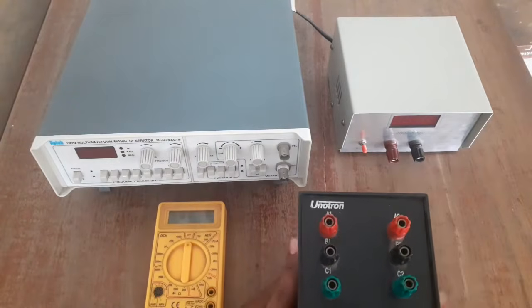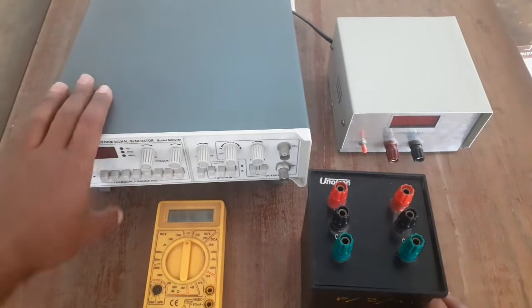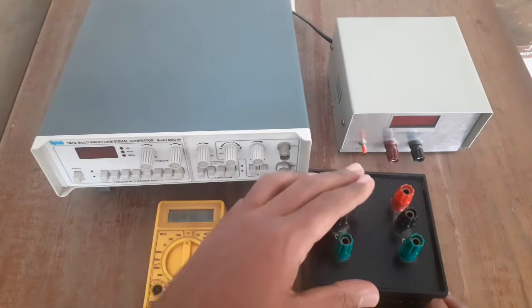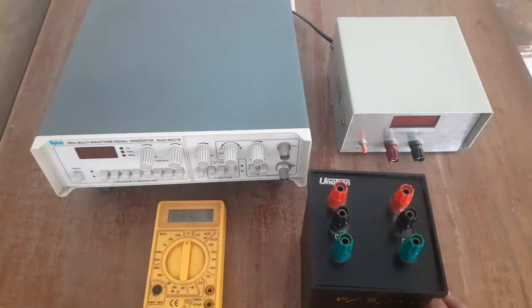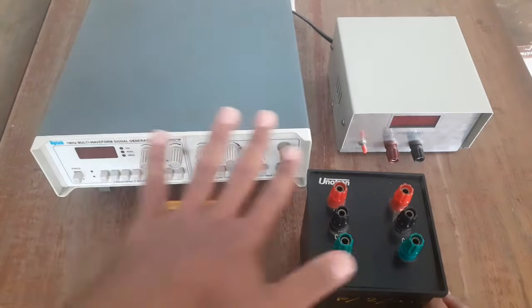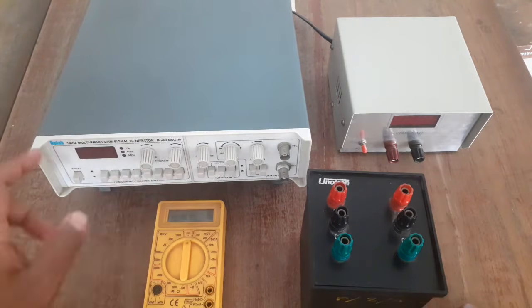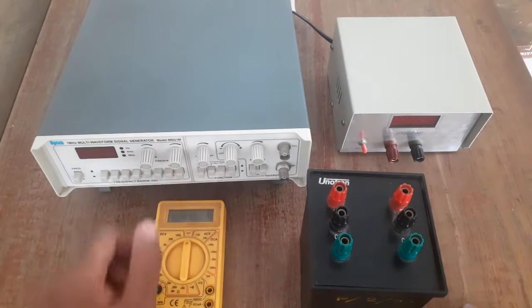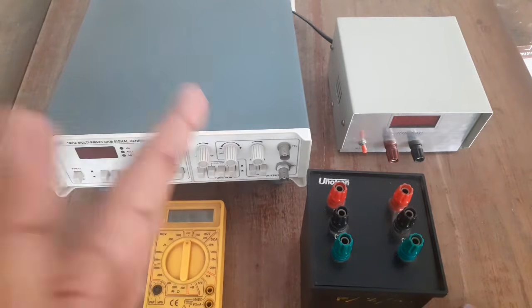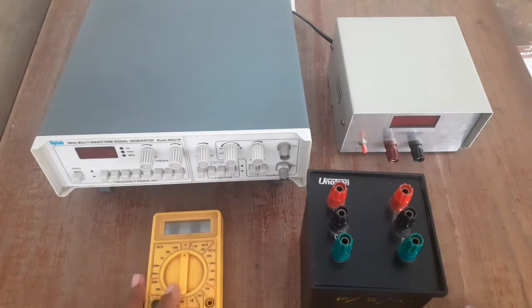To find out, the technique we use is alternating current. You know that when you supply an AC through these components, each one of them responds differently. The resistor will not change any of its voltage or current as you change the frequency. A capacitor, if you increase the frequency, starts allowing the current through it, and an inductor, if you increase the frequency, starts blocking the current through it. It's because in an inductor a back EMF develops, and in a capacitor the displacement current will increase and it starts allowing the current. So let's find it out.